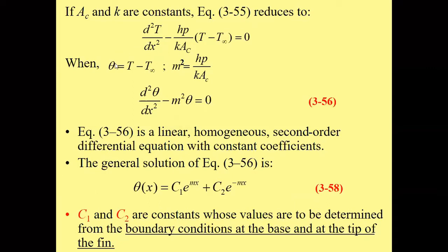And we take this difference, the temperature at any location within the fin minus the ambient temperature, as theta here, right?